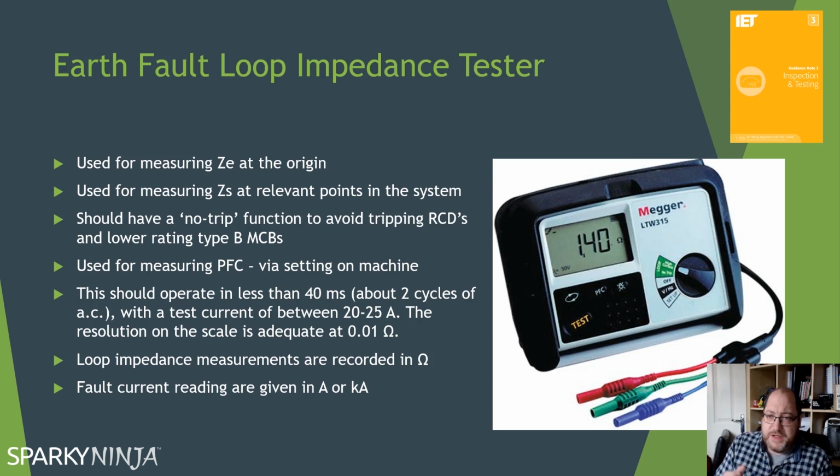So you need to measure Ze on the ohm setting, reconnect the earthing conductor to introduce all of the parallels, and then do the measurement again, but set onto PFC. Sometimes these instruments that have the ability to calculate from one to the other don't really help you, because they try to speed you up when really you're not working competently if you're not aware of these problems.